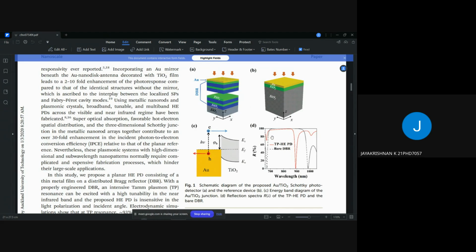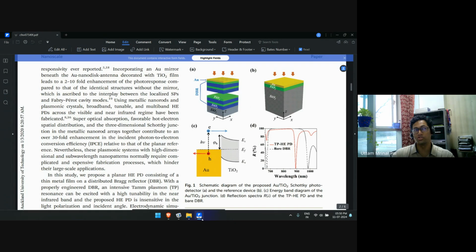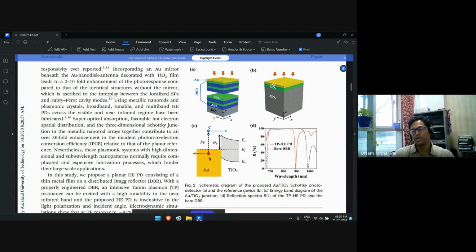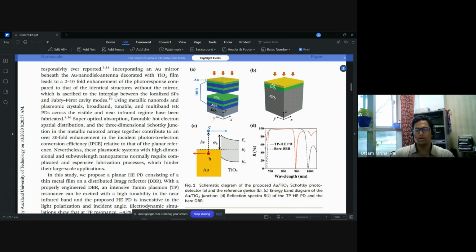For metal, you need to see the skin depth and apply boundary layers. Perhaps tomorrow I can show you how to apply boundary layers. Or alternatively, if you don't want to do this harakiri, instead of modeling volumetric metal, you use TBC, transition boundary condition, and assign the properties of that gold as TBC.